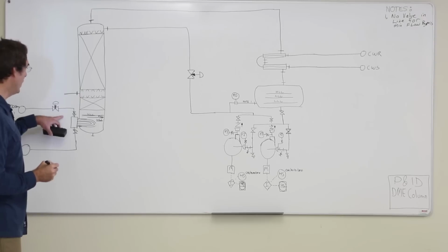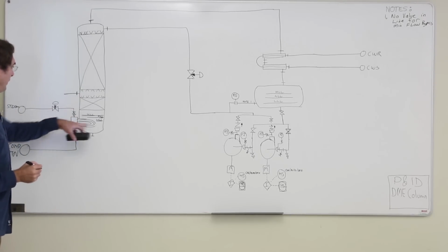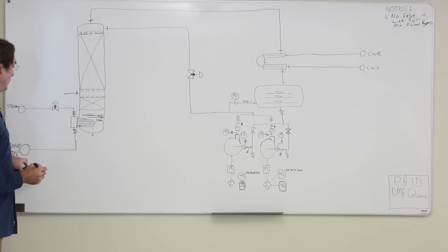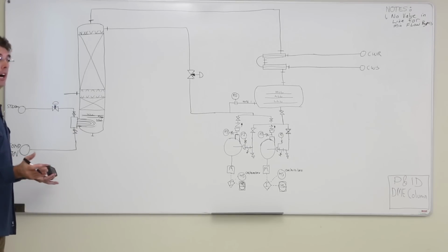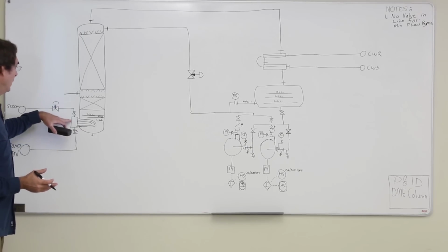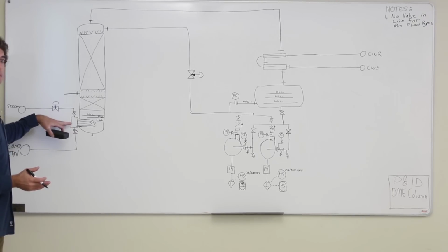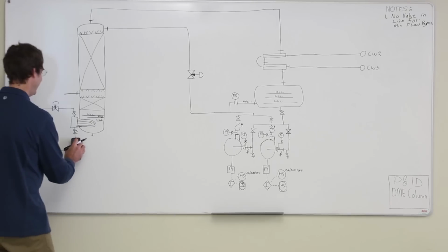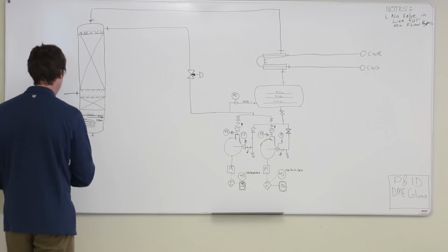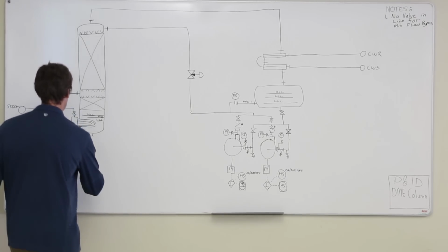And in order for me not to blow steam through the heat exchanger and down into the condensate return system all day long, I need something to stop the steam from blowing through there, but allow the water that condenses in the heat exchanger to go through. What do I need? I'm looking at Liz. You are right. We need a steam trap.